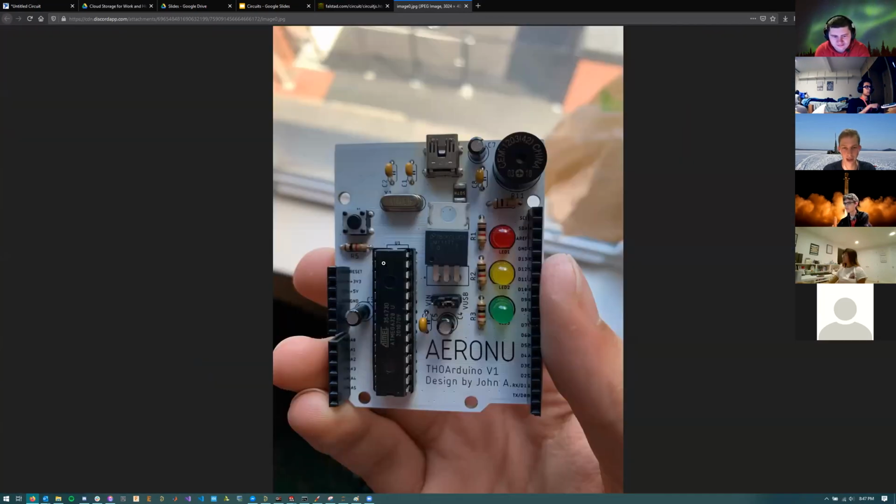They're different types of capacitors, and I can send you something if you're curious about the differences, but they are very different and used for very different things. These yellow ones are ceramic-based capacitors, and these are either 1 microfarad or 0.1 microfarad. We also have some picofarad ones on there too. These two are 22 picofarad, and essentially they are loading our oscillator.